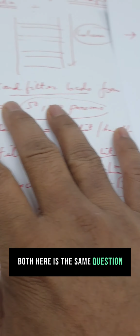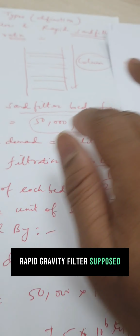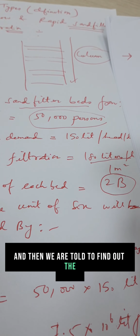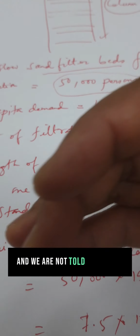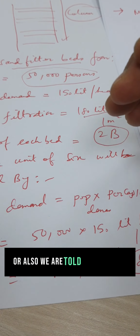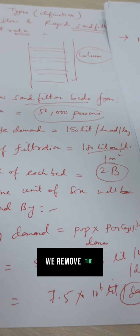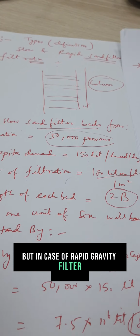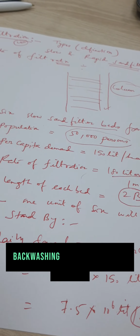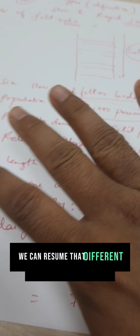Suppose the same question is asked to design a rapid gravity filter. Suppose the population and the same data are given, and we are told to design the rapid gravity filter, and we are not told to keep any unit as standby. Usually in the case of slow sand filter, in the case of cleaning, we remove the top layer. But in the case of rapid gravity filter, since there is the concept of backwashing, usually half an hour is spent in backwashing, and we are told to ignore the time lost in cleaning. In that case, we can assume that the filter operated for 24 hours.